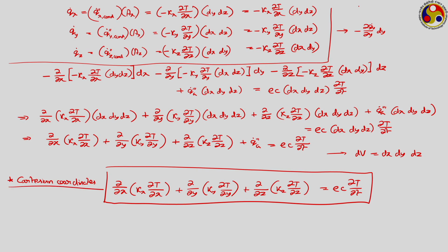So, most of the systems that we deal with are generally Cartesian in nature, so we can use a Cartesian coordinate system, and this equation can always be used there. In certain cases we may have to go for cylindrical coordinates, or in a limited number of cases spherical coordinates. These two we shall discuss in the next lecture, when I shall be developing the generalized heat diffusion equation for both of them. But for the moment, just continue with this heat diffusion equation in Cartesian coordinates.